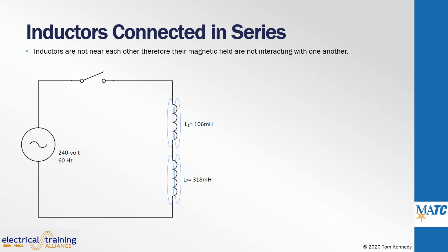The addition of another inductor in series with inductor L1 essentially adds turns of wire to the first inductor, and the same applies for inductor L2 back to inductor L1. So in the end, the two inductors connected in series will have a combined effect and reduce the overall circuit current. By evaluating the opposition to current in this circuit, each inductor will have an inductive reactance. This inductive reactance can be calculated using the 2πfL inductive reactance formula, which is covered more in detail in Lesson 3 of AC Theory Level 1.